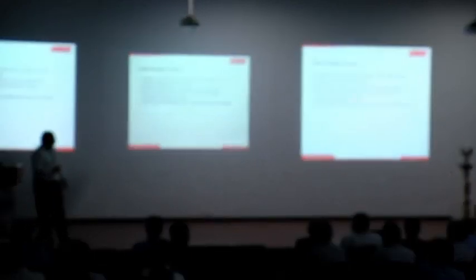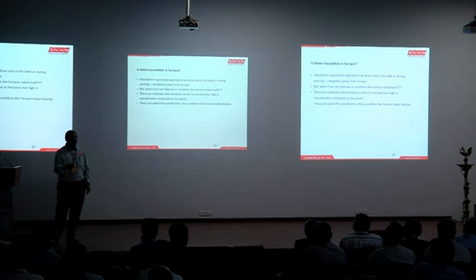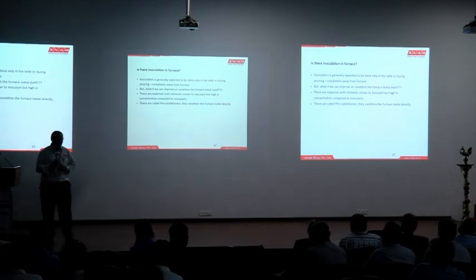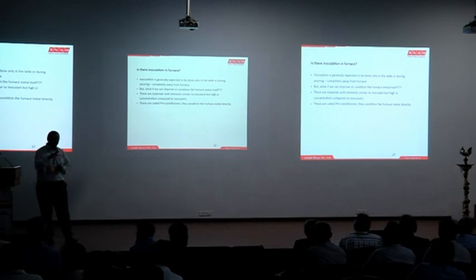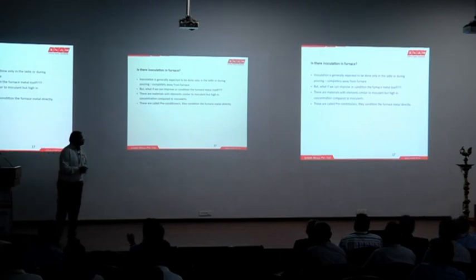There are materials called preconditioners, that means they will condition your liquid metal. For example, Monday, Tuesday, Wednesday, Thursday, Friday, on all 6 days, the first heat will always be different. The first heat, the second heat, the third heat, though the chemical composition is the same, with respect to time, temperature, holding time in the furnace, and melting rate, the potency of the material can vary slightly. And for people who have a holding furnace, there is a tendency that metal from different furnaces can get mixed up, and metal with different potencies gets mixed up. In those cases, to balance the variations, we can do inoculation at the furnace itself. It is called conditioning your material. It is generally termed preconditioners.